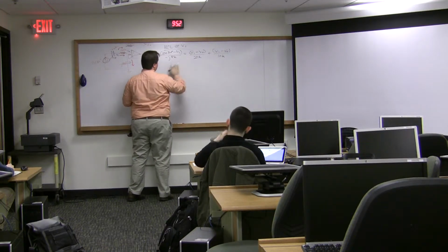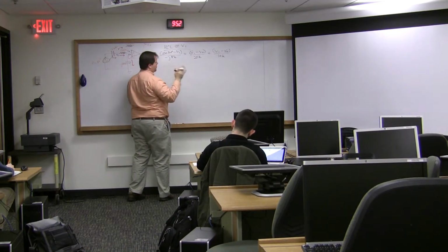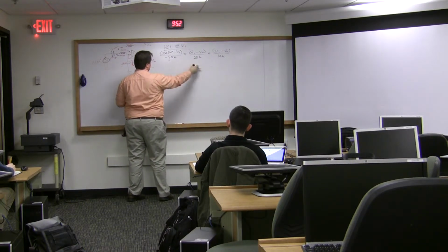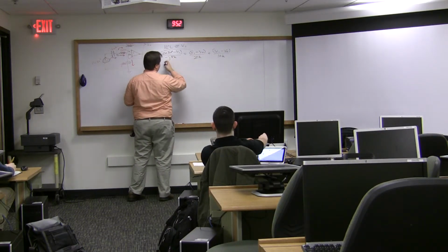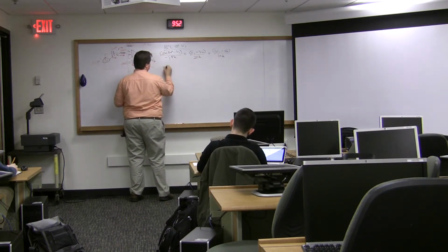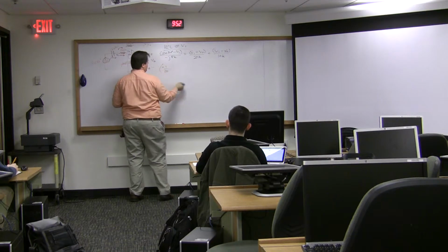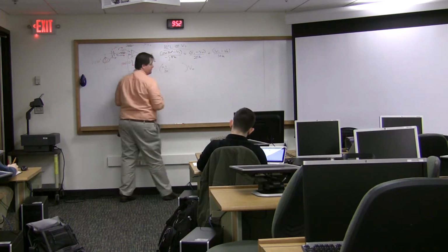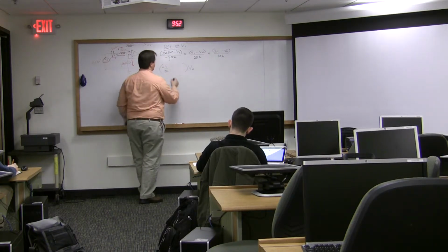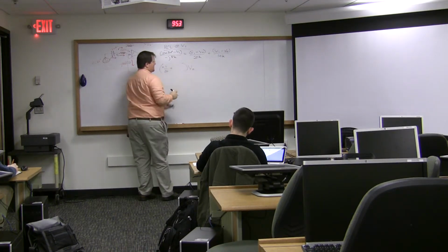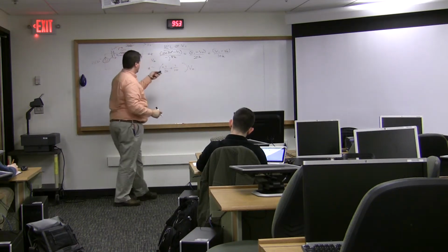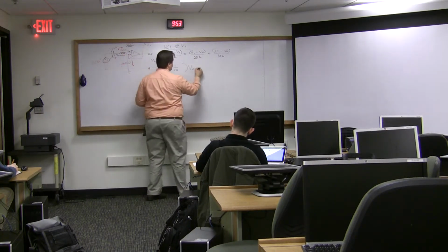Just remember which order you put your coefficients in. If we want to do V0, V1, then when I pull the V0 terms over, I have a negative 1 over 20. That becomes a positive 1 over 20. So this is all my coefficients of V0. This term right here gives me 1 over 10, and it was a negative, and it moves to the left as a positive. There's nothing from this side, so that's it.